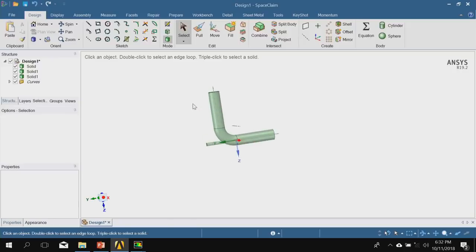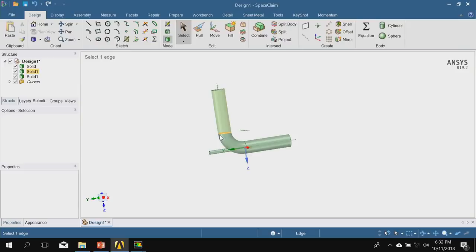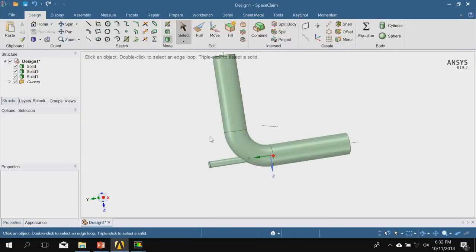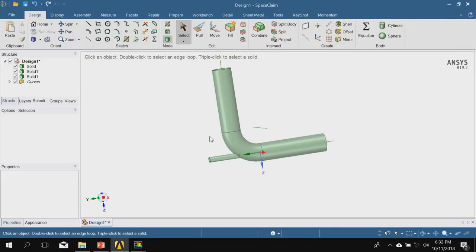If you have a complex CAD model with multiple parts that are adjacent to each other, that have surfaces that are overlapping, then before importing this into Fluent, you need to make sure that these objects are sharing their topology, meaning that all of the overlapping surfaces that are adjacent to each other are fused together into a single surface.